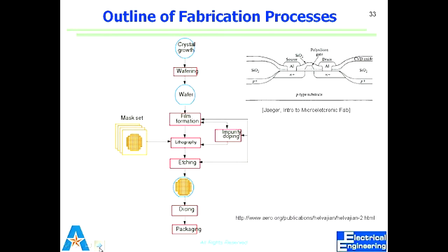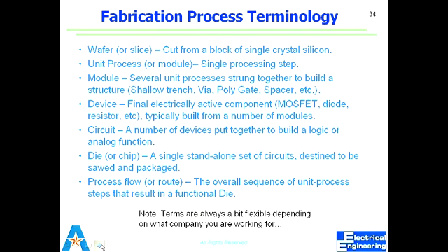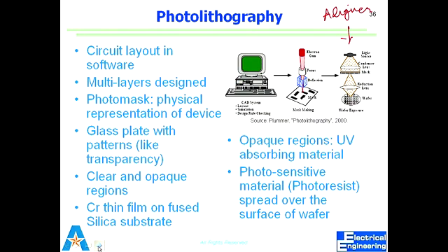What is lithography again? We use these transparent media, which can be a glass plate, to define regions of opaque parts and transparent parts, and we shine light through it. That results in a shadow on a wafer, which is coated with a photosensitive material that translates that image onto the surface of that wafer, and we do whatever process comes after that. So this is again, we have looked at this. So what does lithography do?